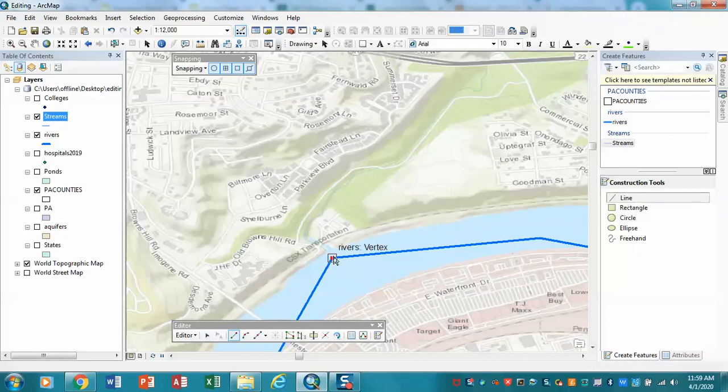start here. And then what I'm going to do is click on the F8 key, and then hold down my left mouse button. And you'll notice that a whole lot of vertices are coming out, but I get a much better shaped line. And so I can follow a very convoluted path with this. And then when I'm done editing, stop here, I'm going to double mouse click again. So again, that is the streaming mode of digitizing.